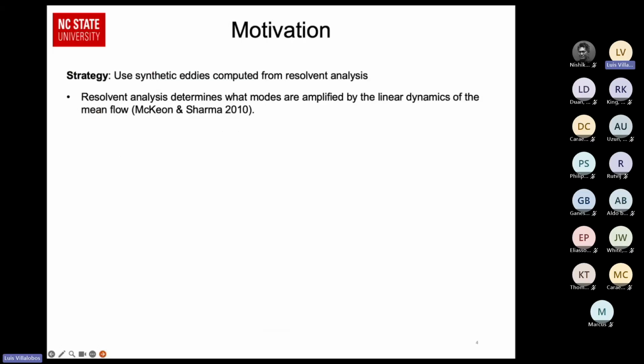Resolvent analysis is a general technique for determining what sorts of modes are amplified by the linearized dynamics of whatever operator that you're working on. So in our case, we're working with a Navier-Stokes operator. So resolvent analysis will tell us what types of modes the linearized Navier-Stokes equations will amplify.